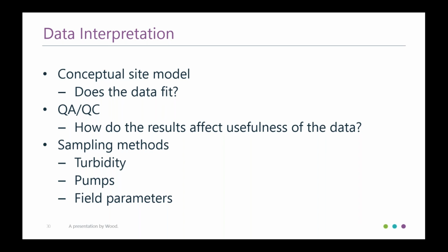Just because it's there doesn't mean the sample has no value, but in some cases with really low detection limits, like for PFAS, a small amount might make your sample invalid and you need to resample. So be really careful: the lower the detection limit gets, the more important it is that you are careful in how you collect those samples and do your decon.